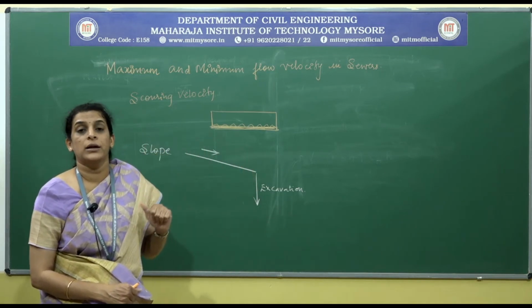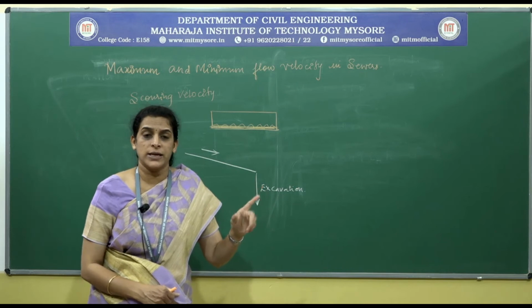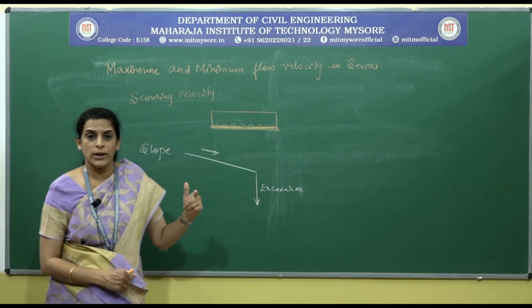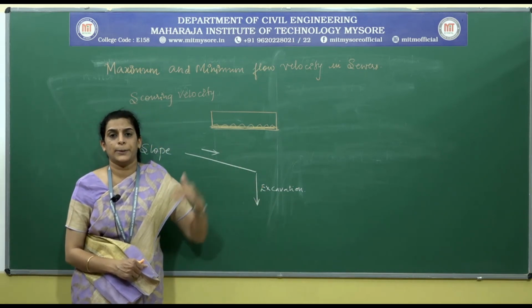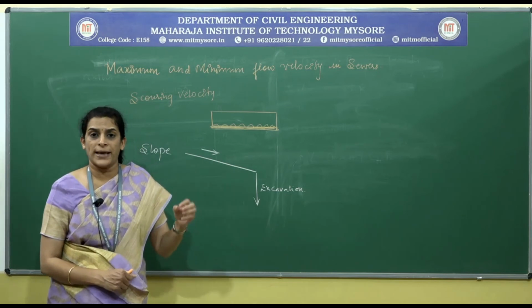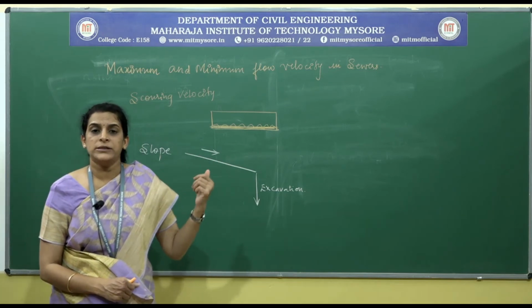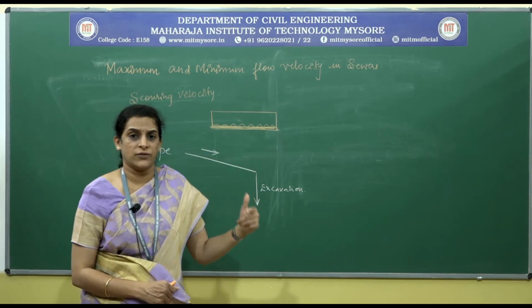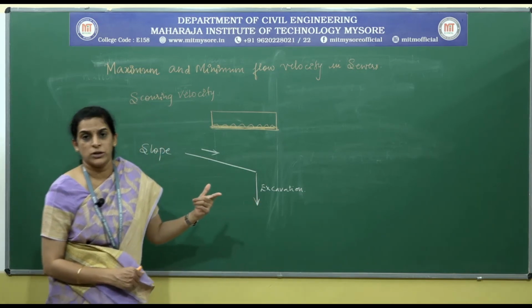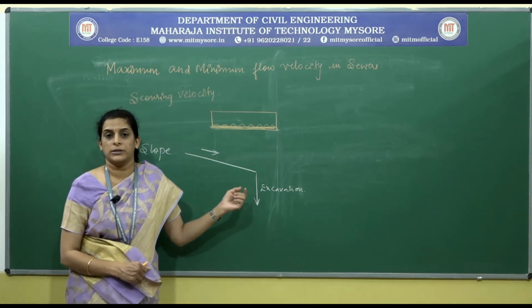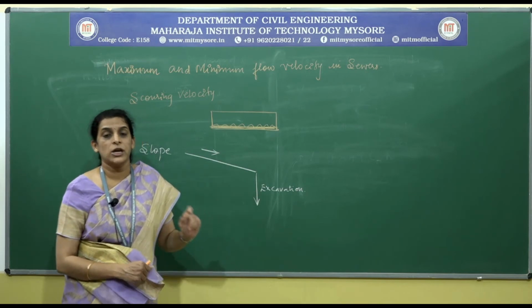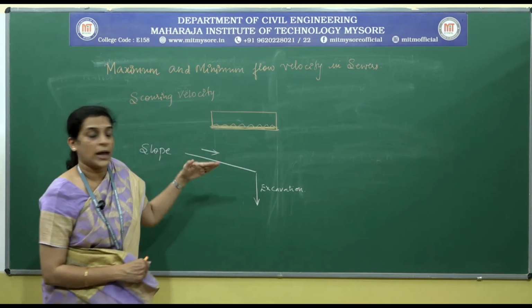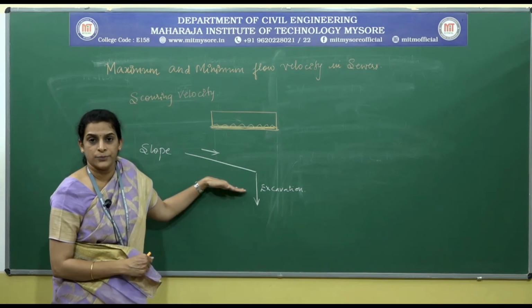Why uneconomical? Because in those instances, at infrequent intervals or in between the intermediate points, we are supposed to place equipment like pumps so as to suffice the passage of sewage. Of course, that is uneconomical. Hence, in those instances, we are supposed to select an appropriate gradient.